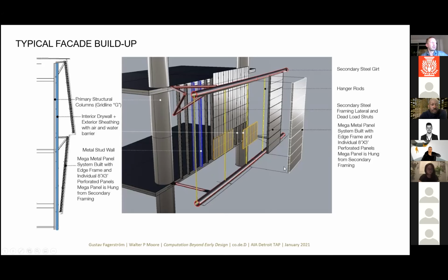Then the lower end of the panels are pinned. It's a little bit hard to see in this view, but you'll see that later on the mock-up picture. So these struts here are pinned so that whenever the wind blows, the lateral forces that affect the building get transferred back here, but any self-weight is taken up, including the weight of the lower hoop, by these hangers and goes back through this hoop and back through these gravity connections here. So this is basically a rain screen, where back here you see those are the cold form studs